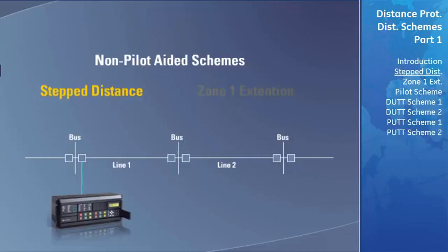The main transmission line we will be protecting will be line number 1, with the D60 located at the far left of that transmission line. The first zone of protection is set to underreaching and extends from the beginning of the transmission line to 80 or 90% of the length of the entire line. This zone is also set to have no time delay. Therefore, if a fault occurs in this zone, the D60 can be sure that the fault is located on its transmission line and can trip immediately.